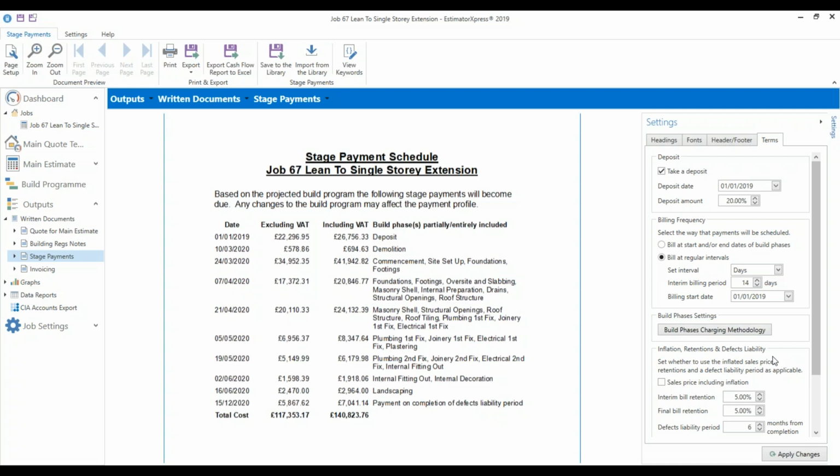Okay, so got a couple of questions coming in. I think I might have answered the first question that came in, about the labour on a price per metre. You could, in theory, do that. You'd probably have to rewrite the labour price book to allow for a per metre rate. But bear in mind what the specification does: it applies a per square metre rate based on the time value they're taking to lay the square metres.